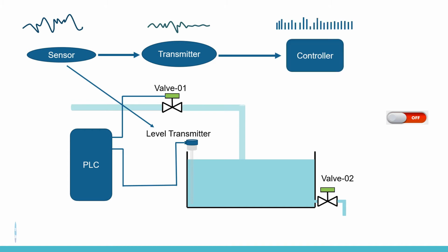2. The PLC controller on the analog input receives the signal in the range of 0 to 20 mA and converts it into a digital value, e.g. 0 to 27,648; it depends on the type and configuration of the PLC controller. To further use this measurement, the PLC programmer must scale it according to the measuring range of the level sensor. The scaled value is saved in the controller's memory for further use.